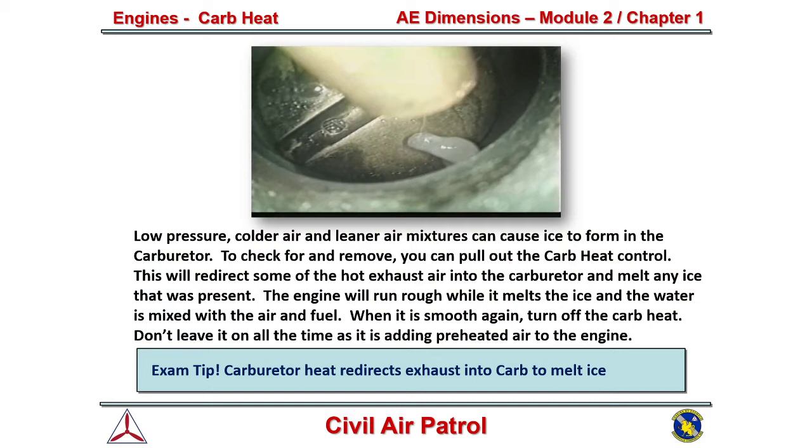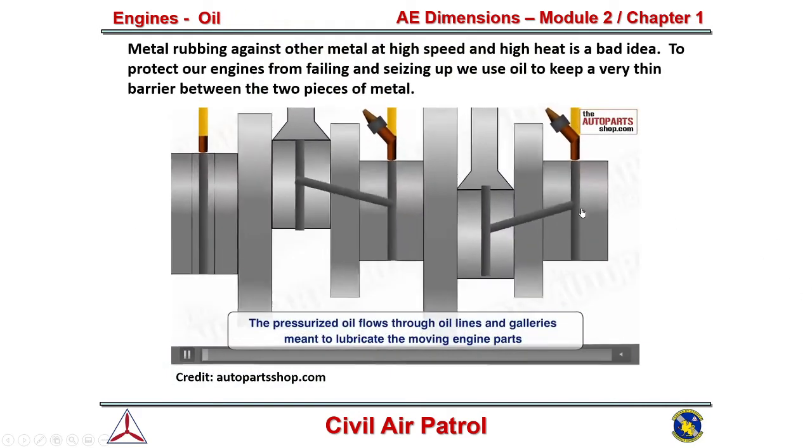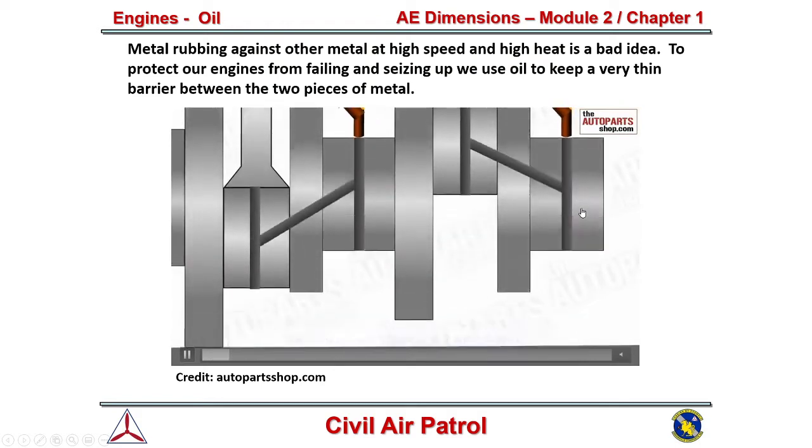So you want to make sure that you don't do that too much. So only put it on when you need it, but don't hesitate to put it on and then turn it off. Again, if you're in a cold environment or an area where you expect that there might be icing, if you start to feel the engine not performing the way you would think, then go ahead and turn it on. If it's running smooth after you turn it on, just go ahead and turn it right back off. There's no penalty for you, really, if you do it in short bouts. Okay. Let's see. Now, one of the last things we have to talk about is oil.